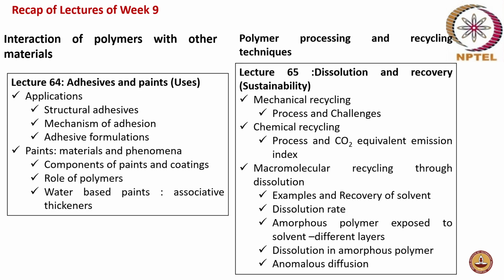And then what is the dissolution rate? So what happens when you have an amorphous polymer exposed to a solvent, you will start forming different layers, and then dissolution in amorphous polymer, and then the concept of anomalous diffusion in polymers, and there was also a highlight on dissolution in case of a crystalline polymer as well. And what is the difficulty in case of crystallinity coming into the picture in case of dissolution also was discussed in detail.